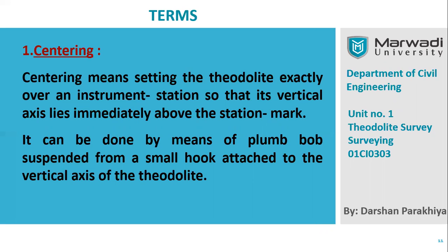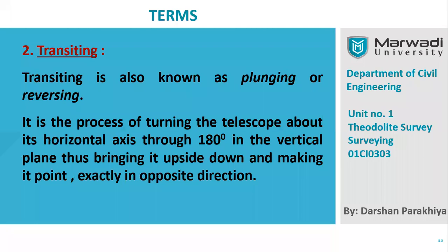Centering means setting a theodolite or any instrument, be it a total station or a dumpy level. Centering means setting any instrument used for surveying exactly over the station, with the vertical axis truly vertical. If station A is marked and we have to set up the instrument exactly over the station, that process is called centering, and it can be done by the plumb bob, as you have done practically in a lab session.